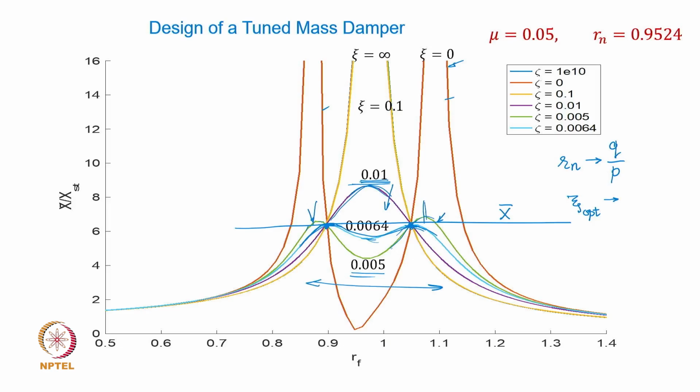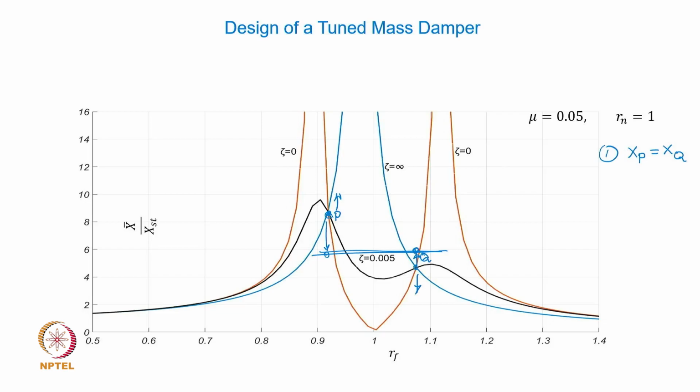Okay, and then the fact that for an undamped vibration absorber, the problem always is large amplitudes at the nearby resonances, and limiting a very strict regime of operating condition that gets relaxed, and then you don't have to worry about resonances throughout the operating speed range. So this is the basic philosophy of the tuned mass damper design.